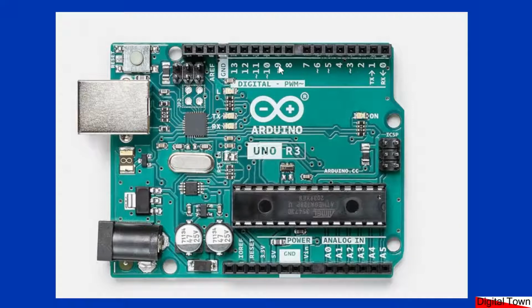Now that 5 volts isn't a particularly powerful 5 volts. It's certainly not going to turn a motor on, but what it allows us to do is turn on a motor driver board. So those of us who are doing the robot car tutorial, it's a way that we can turn a switch on that in turn turns the motors on. We could attach these to a relay that could then control a light. Even a mains voltage light could be controlled through it, and there is enough power that comes out of these certainly to control various electronic components and, more importantly, an LED, so we can make a light go on and off.